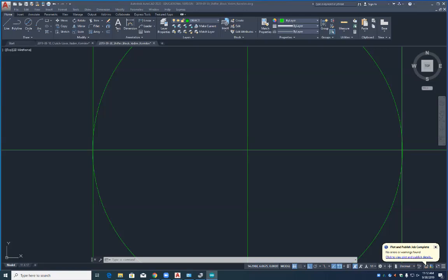0.005, right? Yep. So let's move it 0.005. Now, everyone remembers using the @ command, don't you? That was drawing lines, right? Guess what? We can move using the @ command also. We want to move this hole here that way.